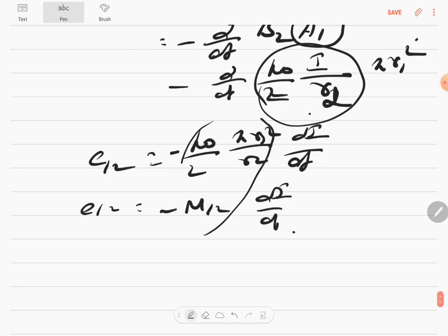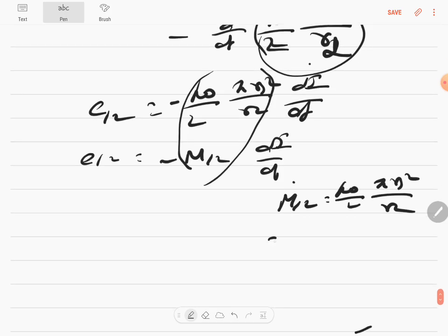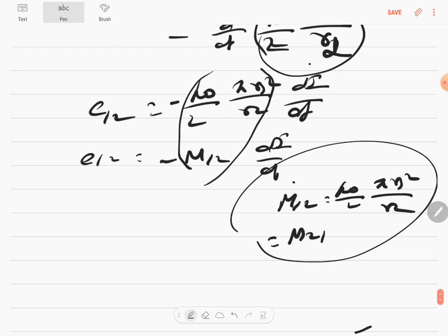So if this is the mutual induction on the first coil due to the second coil, you can write this equal to also M21 for convenience, and they'll write it as the same. Why they can't specifically find out is because the magnetic field of the inner coil is non-uniform to the exterior of it, and so you're not able to write B to be one value. Are you guys clear? So this completes the first class that I took.